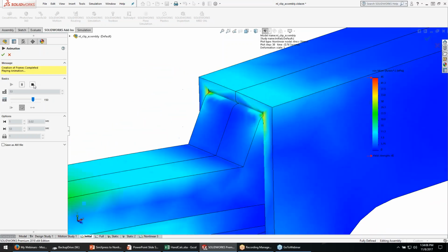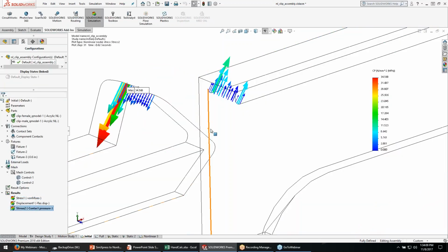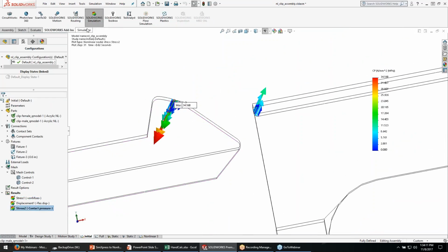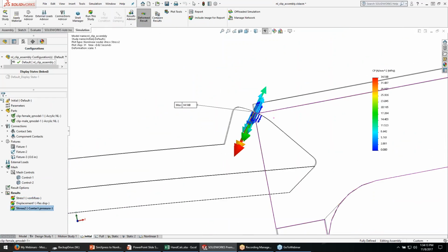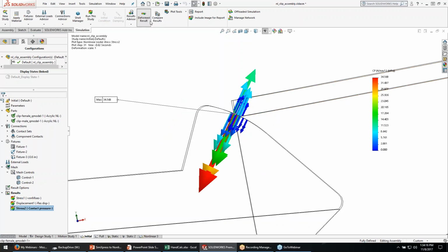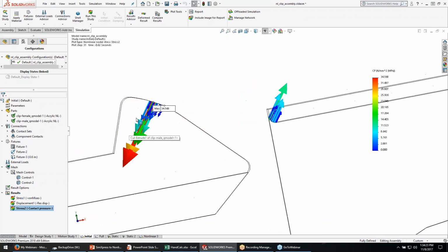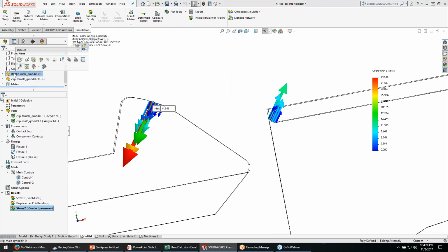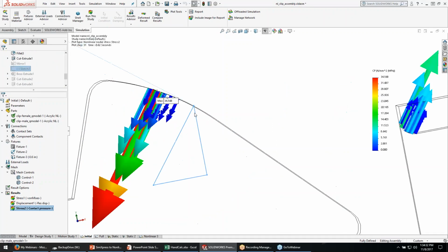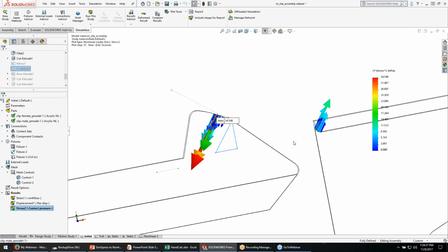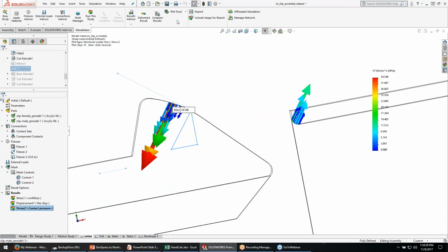Okay. We can also look at contact pressures. Let me show the deformed pattern of that, show the interface there. And I'm trying to look at the contact pressure where it hits its maximum. So if I go back and show you, there's a difference between where I thought, according to my hand calculation, the maximum might be and where it actually came up with a maximum. So if I show this sketch here, I thought the maximum would be right about here according to that little triangle sketch, but actually it's up here. Why the difference? How come I was off by that much?